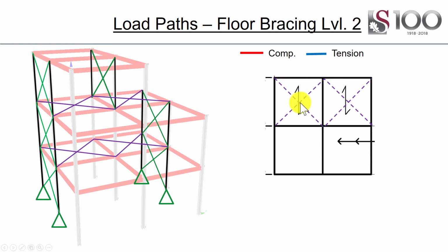So here we now have our floor bracing. I'm designing this section now, and once again, this section is supported by the vertical braced bays, here and here. Now I could, if I wanted to, move those supports to the far side. There's absolutely no reason why not. In this model, I'm just being consistent. So if I put the support here, in the next model, I will use that same node.